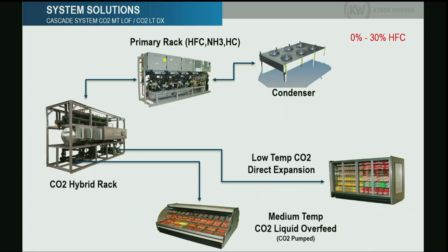This is a new version of the CO2 system when we kind of reduce that complication a little bit. So this system here, we call that CO2 hybrid because in here we have compressors on this side and we have the liquid CO2 pump on this side. So this system can provide liquid overfeed for medium temperature and can provide CO2 direct expansion for the low temperature application.